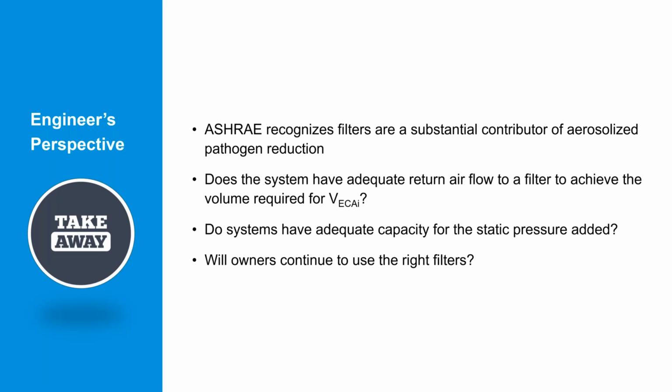I did an event about a year ago where I was speaking to testing and balancing contractors, and I asked how many people were asked to increase their units from whatever pre-filter to a MERV 13, and almost every hand went up. I said, how many of them had problems with the MERV 13 they added to their rooftop units? And all the hands stayed up. And so we understand that adding these additional filters can stress the fan and could potentially create problems. And so that's where the building owner and the engineer have to get involved and decide, do you add something new as it relates to a piece of equipment? And when you do, do you add the capability for you to swap in an upgraded filter when you want to go to your IRMM such that you can manage that additional static pressure?